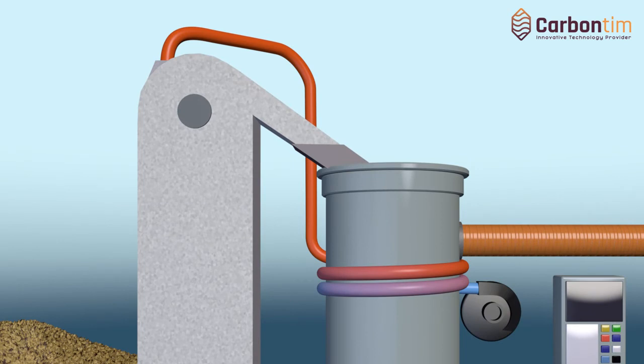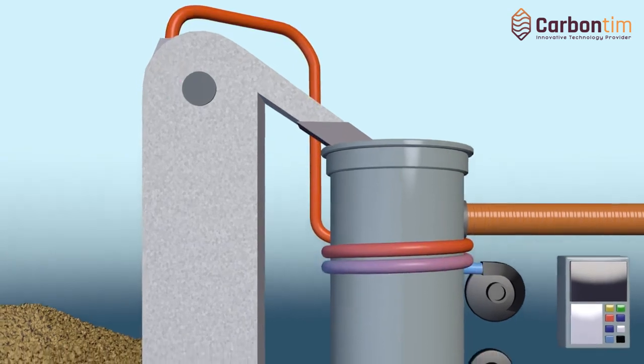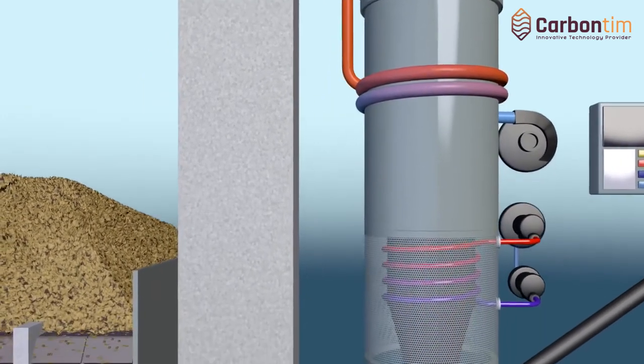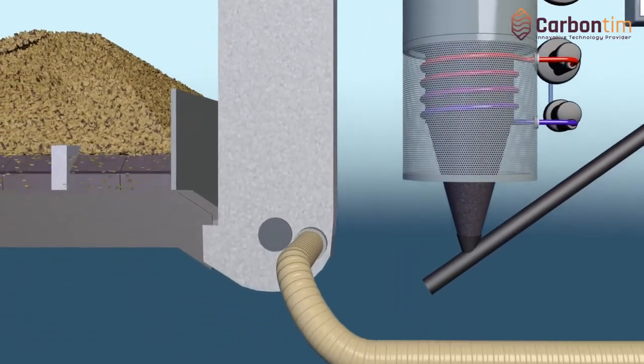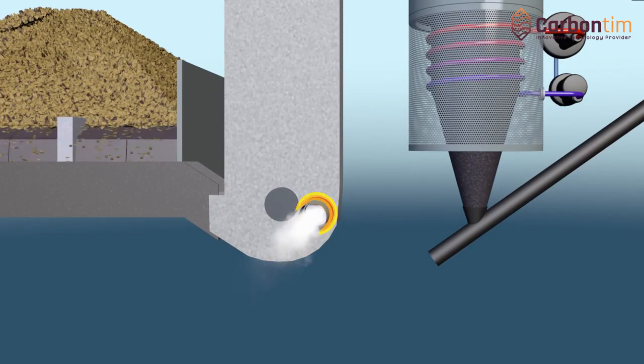In order to maximize the efficiency of the pyrolysis process, hot air taken from the coat of the reactor is used in the biomass pre-drying process. Hot air is transferred to the bucket feeder, which was illustrated some time ago. At the end of the process, all gases are mixed and emitted through the common stack.